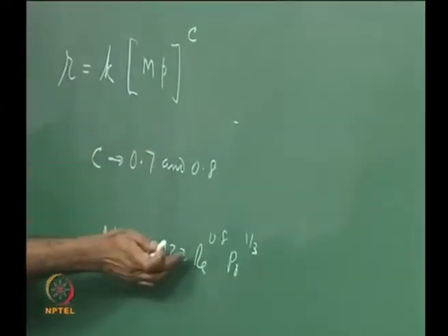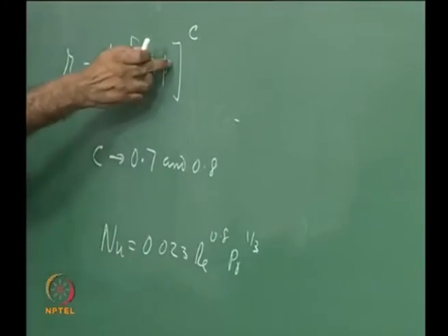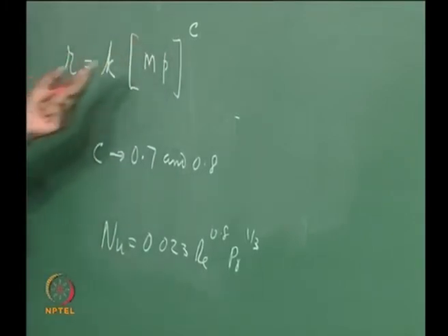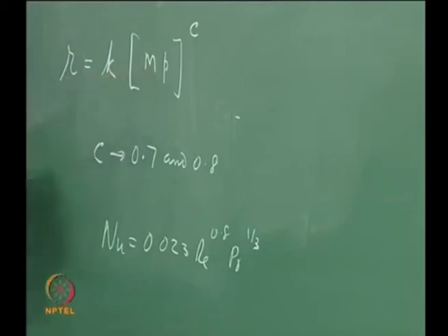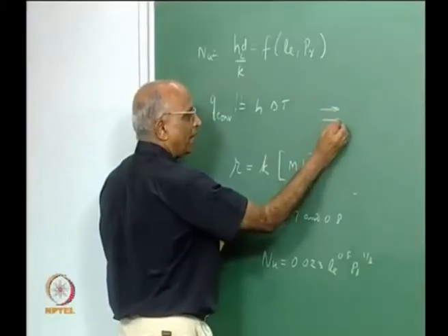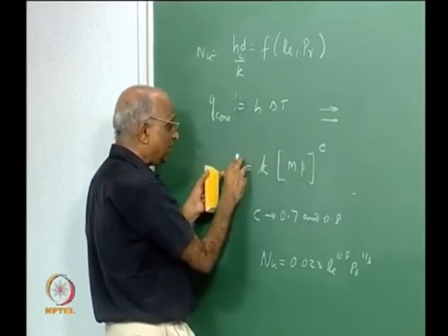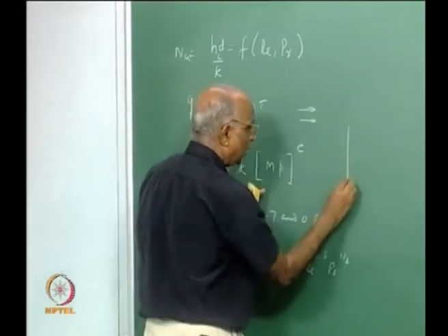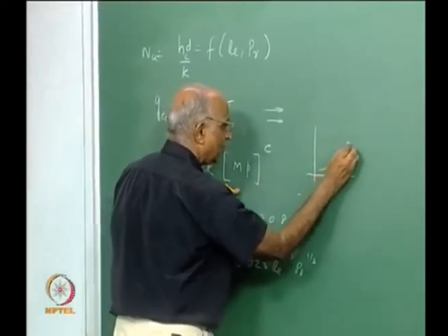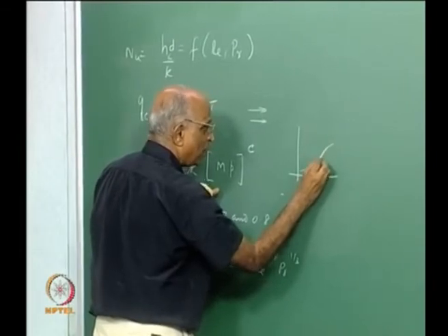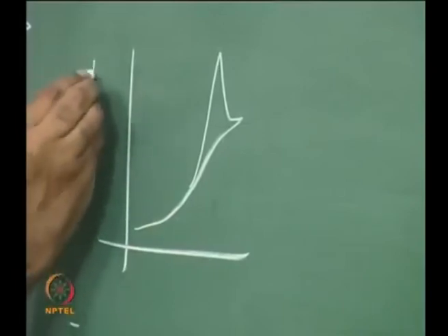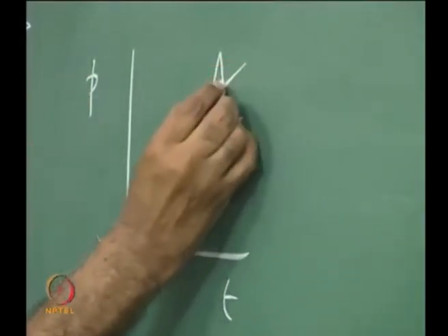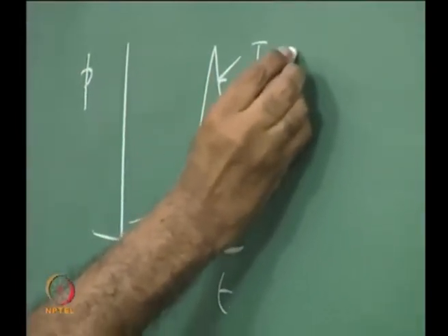That means it does show that convection plays a role. In addition to pressure, I have Mach number effects, and this is what gives me the erosion effect. And this erosion effect, because it increases the burn rate, can also lead to, instead of the ignition going like this, at this time the port volume is small, I could have an ignition spike, that is pressure versus time, I have an ignition spike over here.